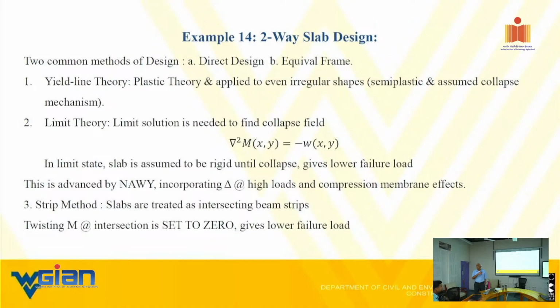This is the reason why we have so many knockdown factors, you see. I'm hoping that even about half of the strength you have today will remain 100 years from now. That's the idea of having knockdown factors. This whole concept of knockdown factors for civil engineers, not aerospace, is only in the last 10-15 years. Remember, before that, nobody even thought about it.